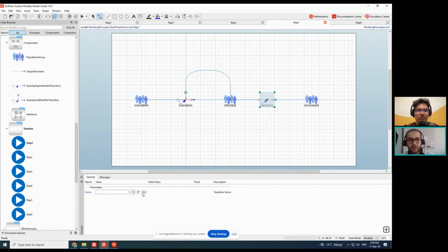Oh, right. So this is what happened, Leo. Our units changed. When we had 0.1, our units actually changed here. So I think we should have 0.1 written like this, 0.1 per day. When we had this as an expression, 1 divided by 10, it went back to its base unit, which is always the SI unit, seconds, so 1 per second. But here, we should use the numeric values, so it's like 0.1 per day. Hopefully that should fix our problem.